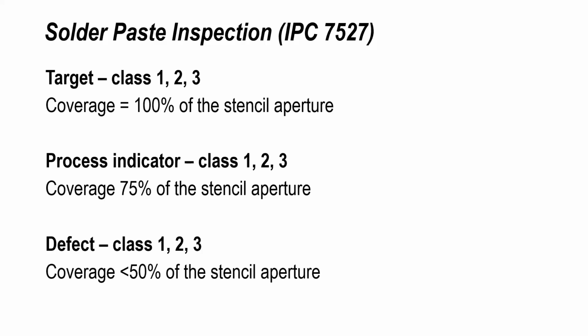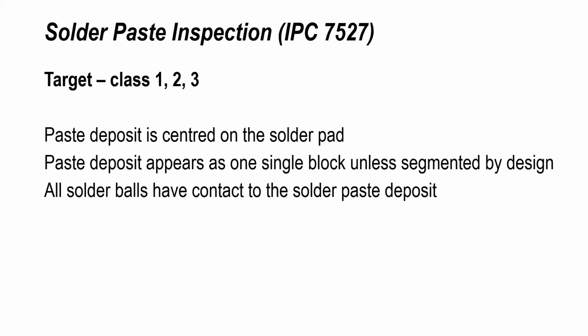A lot of stencil printers produce inspection data, and that's obviously the area of coverage, but it's the SPI which gives you the volume information as well as consistent height measurement. And that's why there's been a trend to use SPI on more advanced circuit boards today, rather than just the area of coverage that we would generally do during optical inspection.